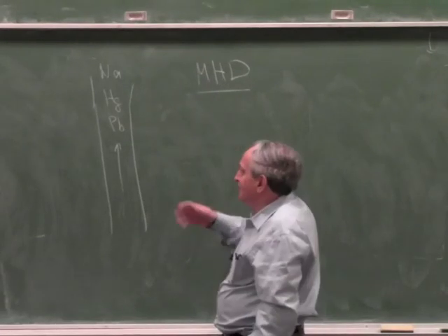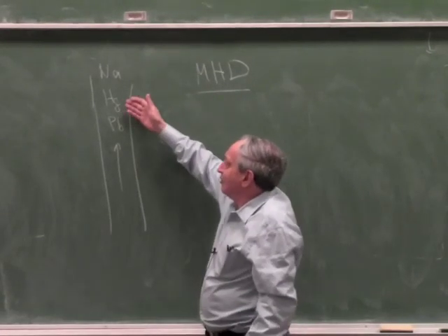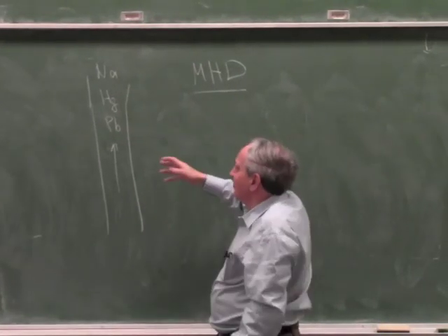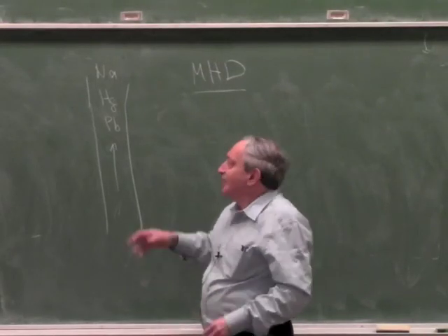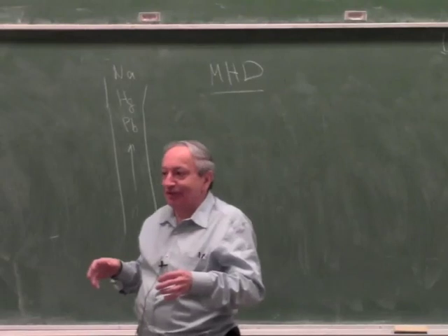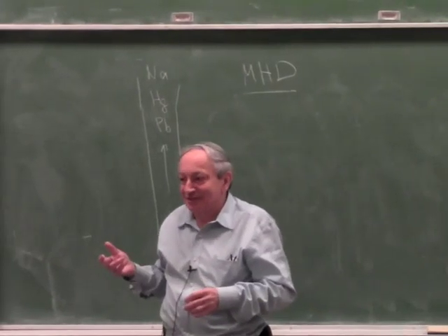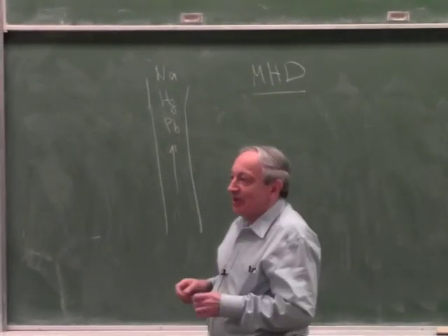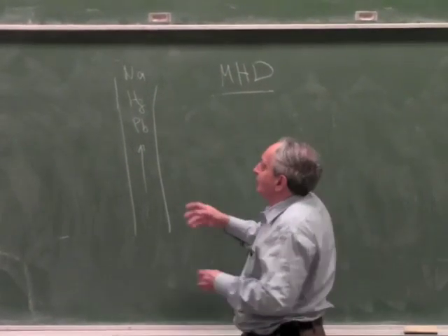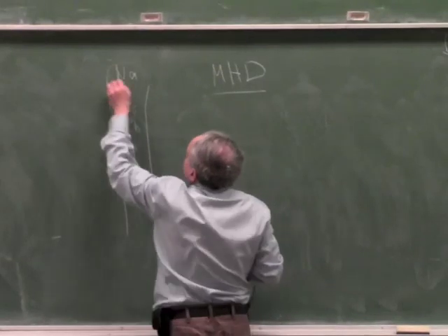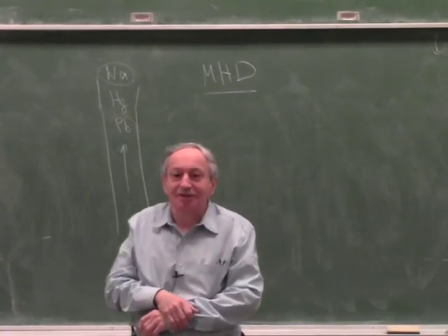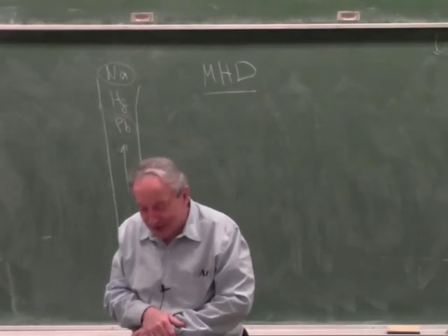Because first of all, these metals are hot, not mercury, but molten lead, molten sodium, these are very hot. Secondly, there's a problem with this, because once you stop the system, these metals which are hot will solidify, and the pump will be full of solidified metal. You wouldn't be able to restart it. Okay, so it's actually quite a big problem. Now, does somebody know why that is important? Where do you pump, especially these two metals, molten in pipes? It's a very big application. Yes? Nuclear reactors? Very true.